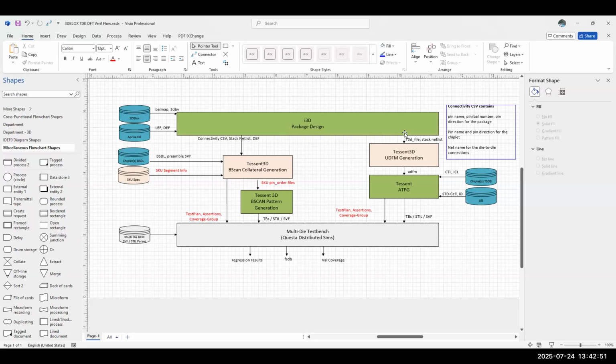Tessent has it as a text file. User-defined fault model, kind of a JSON-like format. Tessent follows this across the different ATPG bundles, like cell-aware and regular ATPG also. So this is not an IEEE standard. Do Cadence and Synopsys support this? I think user-defined is supported by all main CAD vendors. Everybody may have a proprietary format, but it's like cell-aware or user-defined.